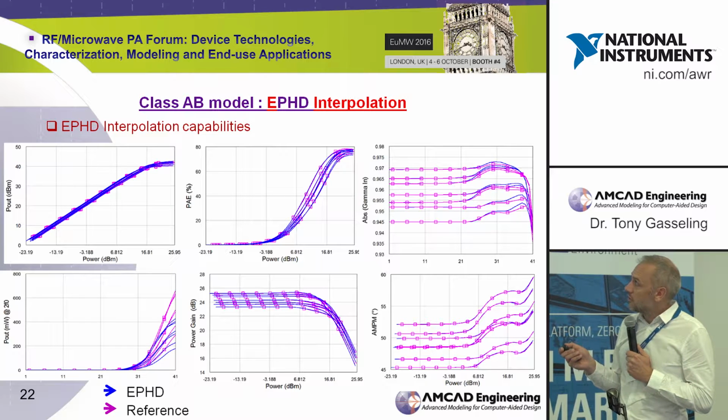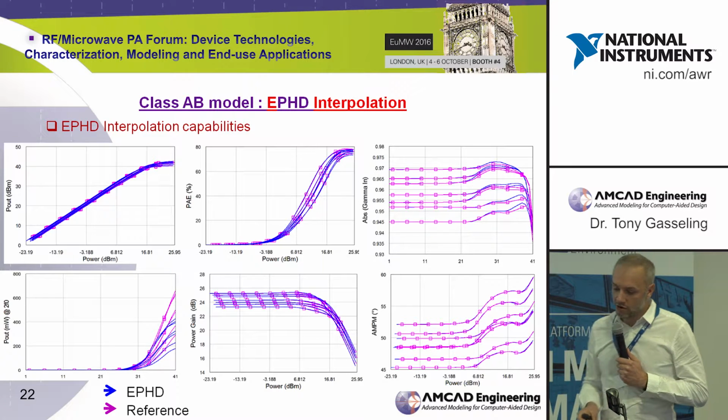Maybe this parameter looks a bit exotic for some of you, but it is very important, because if you are able to fit well the input impedance of the transistor versus the power level, then you have a very good chance to fit well the transistor power gain.